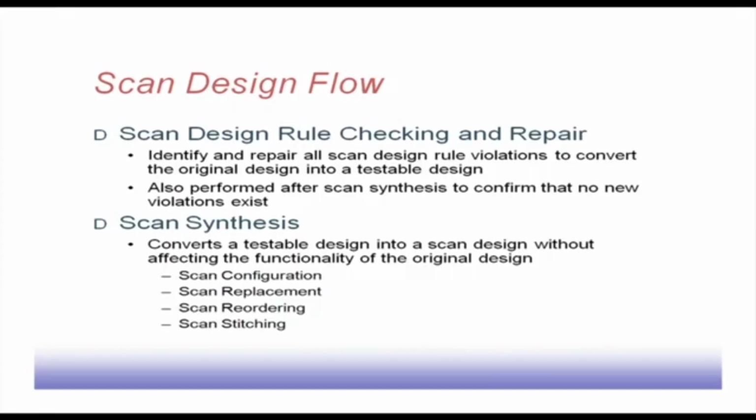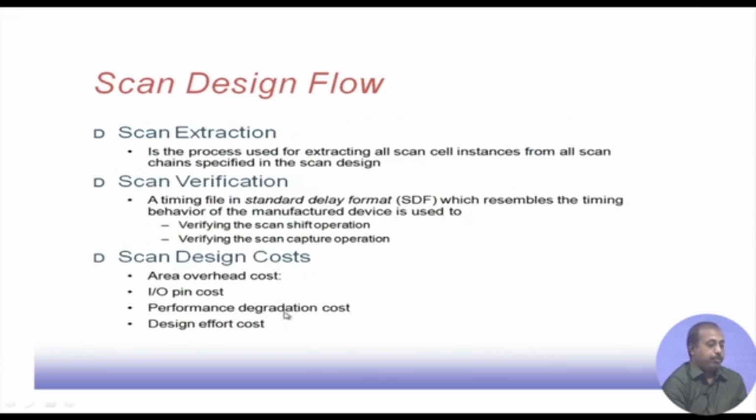Then scan synthesis will convert the testable design into a scan design without affecting the functionality of the original design. So the flip flops will be converted to scan flip flops, the scan stitching and all that. These are the various stages in it: scan configuration, replacement, reordering and stitching.